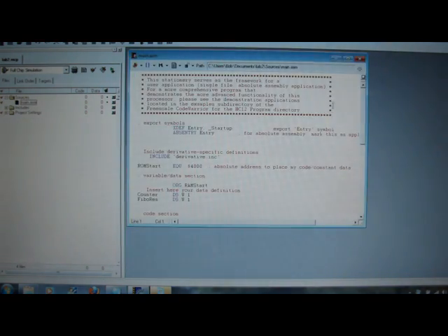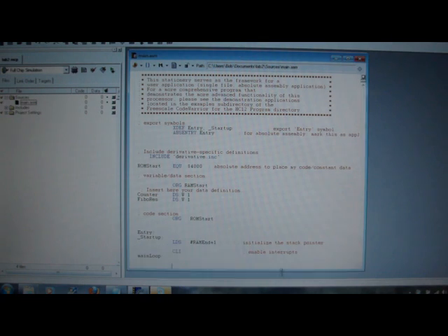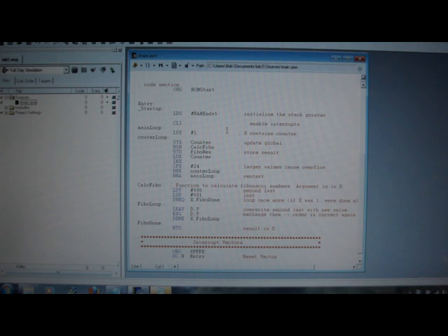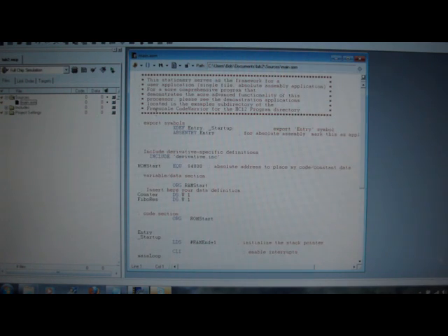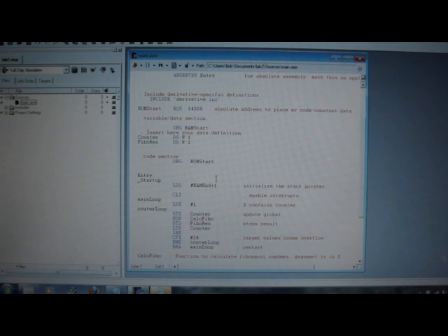So let's double click on that, and notice that what CodeWarrior did was actually fill in a whole bunch of stuff for you. Now, it also puts in a sample assembly language program. This assembly language program begins at this LDS statement right under entry startup, and then all the way down to just before the interrupt vectors area. It also has a bunch of other things up here that's called startup code initialization. We don't want to delete or alter that in any way.